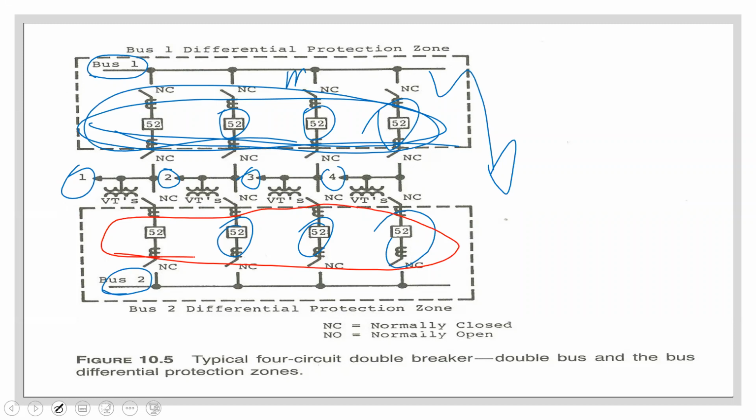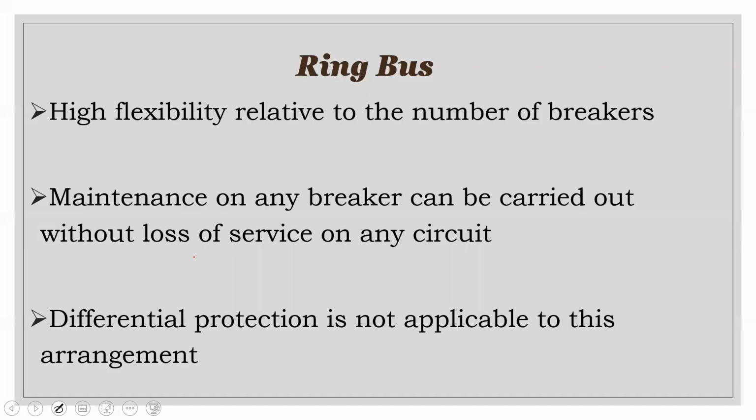All right, ring bus, high flexibility relative to the number of breakers. If you take out a breaker, nobody would know. But we have some other protection issues. Again, don't worry too much about that. But we can take out a breaker and the supply is maintained.